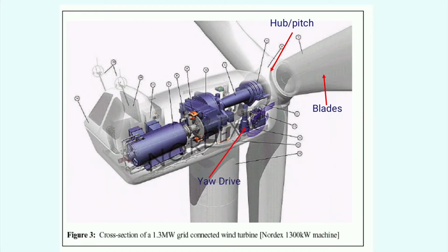To keep the rotor aligned with the wind, electrical motors or yaw drives are required to rotate the nacelle. These do not operate as frequently as the pitch motors, but nonetheless need to withstand large loads as they move the nacelle around in a turbulent wind. This loading can cause wear to the yaw motor or the yaw mechanism, which usually has a small gearbox. Excessive movements can contribute to premature failure.